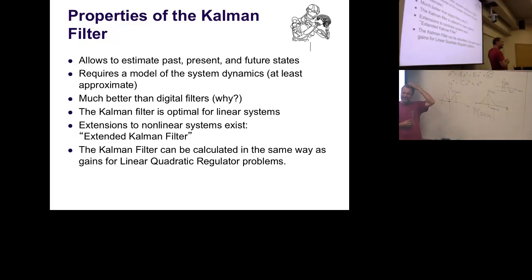And that kind of makes extended Kalman filtering partially complicated. So you have a nonlinear system, you basically linearize it and assume noise gets pushed through in an additive way. In the real system, it's actually pushed through in a nonlinear way and changes the distribution. And then when you do estimation, things can go horribly wrong. And then people have all kinds of cool filters.